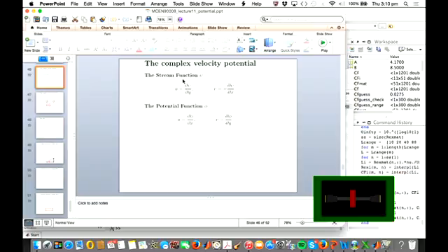And the drag kind of goes through the roof when, I mean, this is the stall, right? Yeah, this is the stall. And the drag goes through the roof. So the key thing for an aircraft design is the lift to drag ratio. And you can see that also stops being favourable once you exceed that stall point. Yeah, I got it. Yeah.